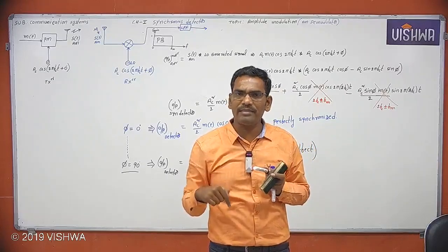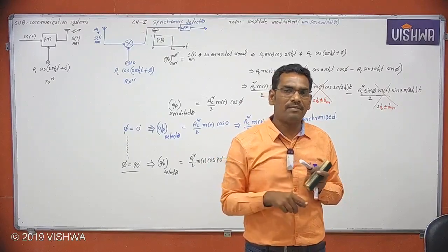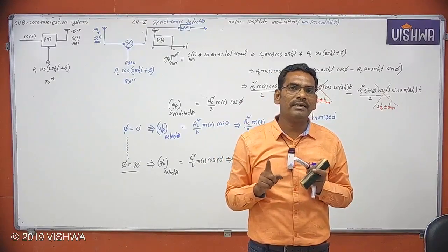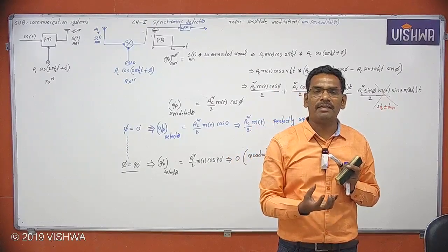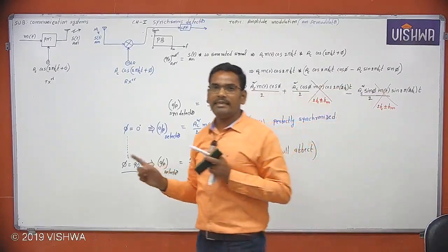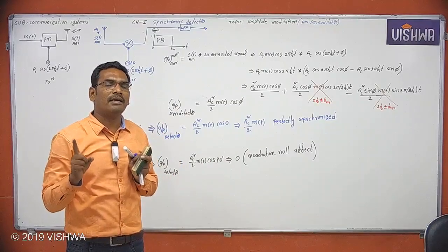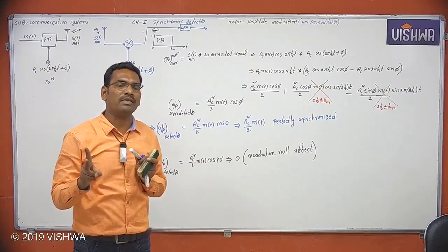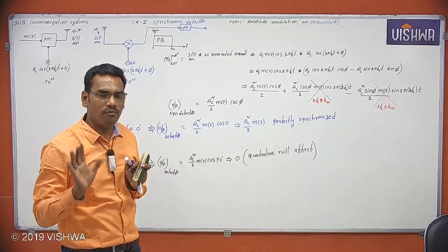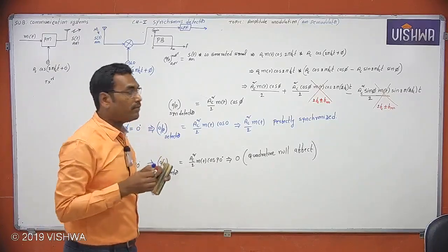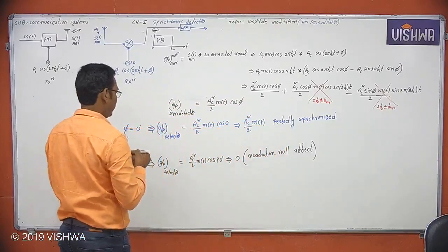So we already fixed in our mind that practically the demodulation of AM is done by envelope detector. If your demodulation technique of AM is only by using envelope detector, you can get n number of advantages. To gain those advantages, at the transmitting side you add a suitable DC component such that demodulation is always possible by using envelope detector, because the modulation index should always be less than or equal to 1. That is the reason why the synchronous detector is not preferred practically.